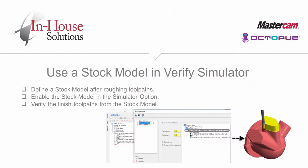In the next step, we are going to learn how to use the stock model in Verify Simulator. You will create a stock model after the OptiRough toolpath and use it as a stock in Verify to simulate the finished toolpaths. This option allows you to save time when checking toolpaths in Verify. You won't need to wait until the roughing operation is simulated.